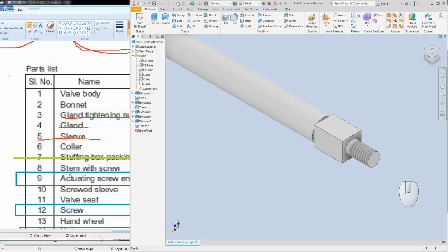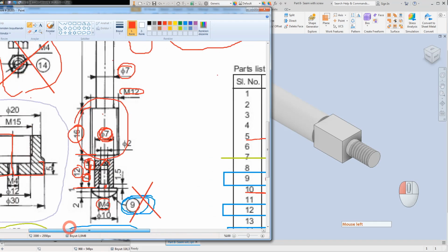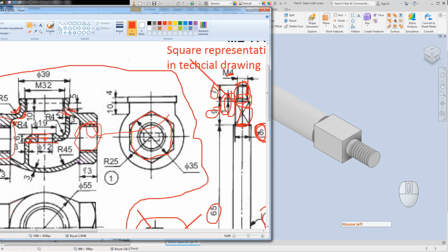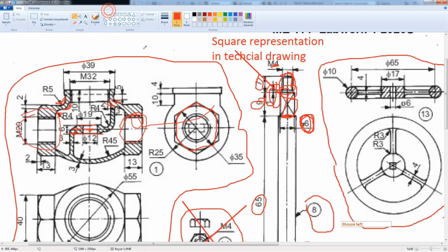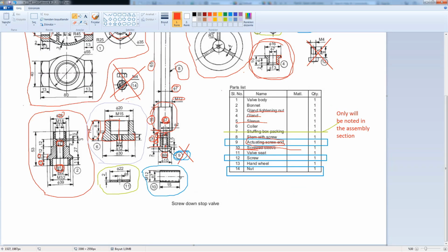Next, we have an actuator screw end, which we will just bring, this bolt or screw, from the library content center. I will just make the next part number 10. I'll search for it. I think let's make the bigger side. Okay. This. It's a very simple part with 15 millimeters, metric 12 threaded on the outside. We have a hole with 7 millimeters.